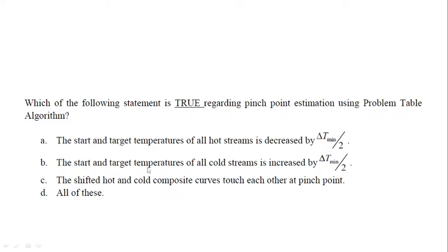The start and target temperature of all cold streams are increased by delta T min by 2. The shifted hot and cold composite curves touch each other at pinch point. Option D, all of these. Actually the answer for this one is option D.